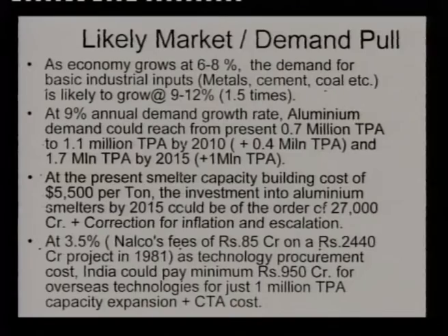If the alumina concentration is too high, then it will exceed the solubility limit, and it will precipitate out as a sludge. There are all kinds of problems. So, it has to be a very narrow window of 6 to 8% or something like that.